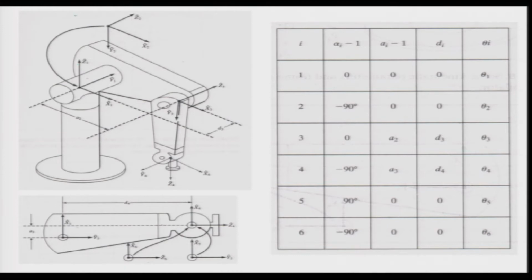So first there is a 0 axis here. So 0 and 1 axis can rotate about this, that is my 0 and 1. The first axis is along this, 0 and 1 we can take it. So this is my waist axis. So let us assign 0 there and 1 there. So it can rotate like this about the waist axis, which is here, the vertical axis. The second axis is the shoulder axis, which is this one. So this is my shoulder axis, which we can call Z2. The third is an elbow axis, which is Z3 here. Okay. And this part is shown here for clarity.